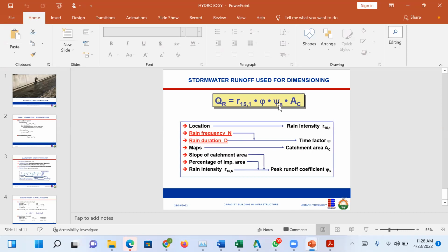Currently in a place like a hotel, where 60% of the land has been used to build the main structure, and 20% of the remaining area is asphalted, what do you think is the coefficient of runoff of this building where I am? It will be around 0.9. Yes, 0.9. Now, if I go to my village, everywhere is farmland, thatch roofs. What do you think will be the runoff coefficient? Between 0.1 and 0.2.